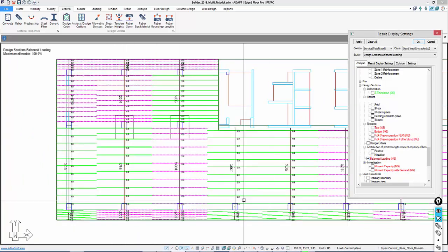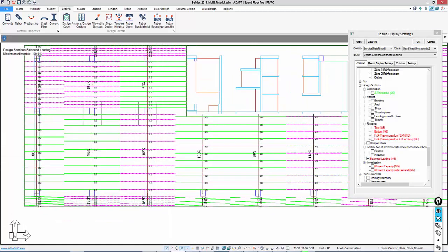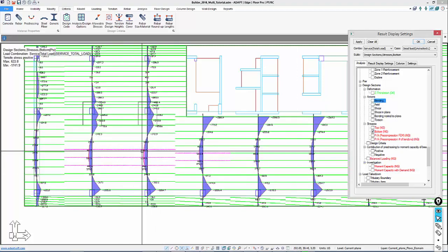Going back to balancing, we do have an overbalance here, but we also have a situation where we have too much tensile stress. So we can't move the cable up to compensate for balancing, otherwise our stress would increase. This is a case where the outcome of the design might be such that the load balancing maximum value that we've targeted is exceeded, and that would lead us into checking the deflection under sustained loads or under service level load conditions to make sure we don't have any crowning in the slab.